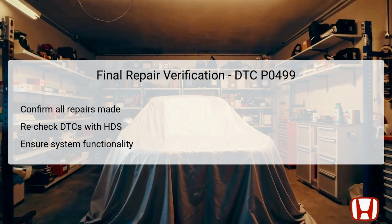Upon completing all necessary repairs associated with DTC P0499, verification of the work is crucial. Begin by confirming that all the repairs or updates have been properly executed according to the troubleshooting steps outlined. It's essential to recheck for any diagnostic trouble codes with the HDS to ensure that the previously identified issues have been eradicated.